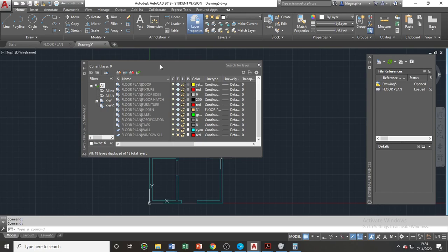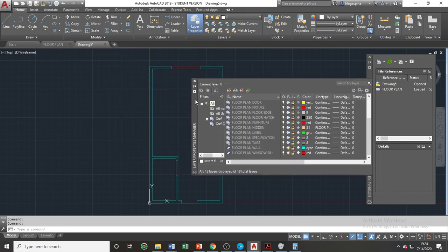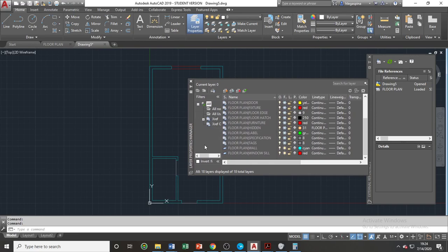For your architectural base plan, in engineering drawings, it is important to emphasize the elements based on the particular engineering drawing being presented, which means that the architectural elements should be presented in a lighter line weight.